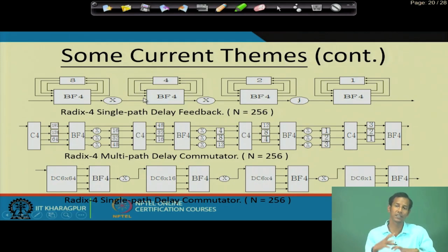So, this is the mixture structure of serial as well as parallel. According to the FFT architecture we have discussed, whenever we use more radix or the serial implementation, the number of processing elements, or the area requirement, will be lower, but the computation time will be slower.